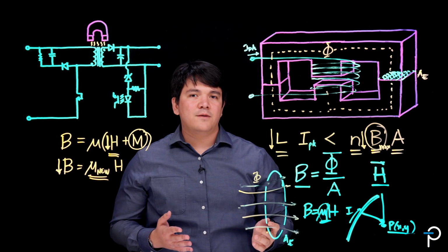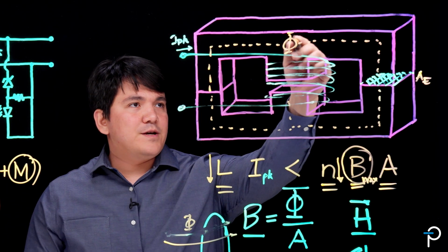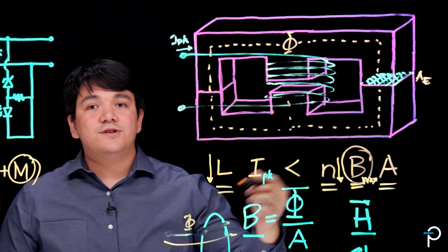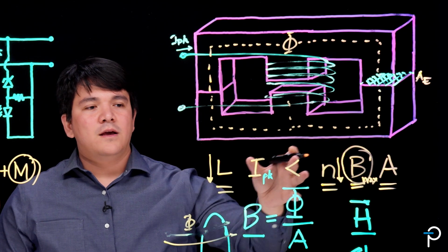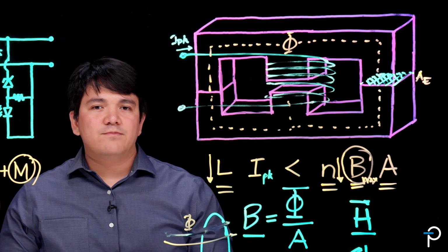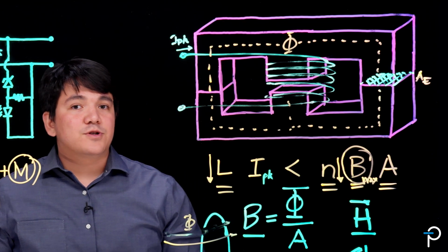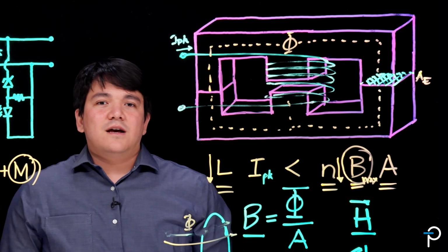If it does still deliver power, because you have fewer flux lines available in your core, it's easier to fully magnetize the core. It's easier to saturate the core. And that would result in warmer MOSFETs, a warmer transformer in general, which would compromise efficiency. You'd get increased thermals. It's non-ideal.